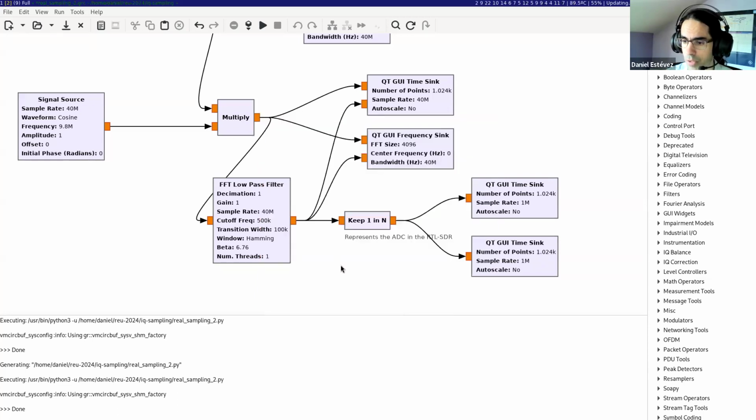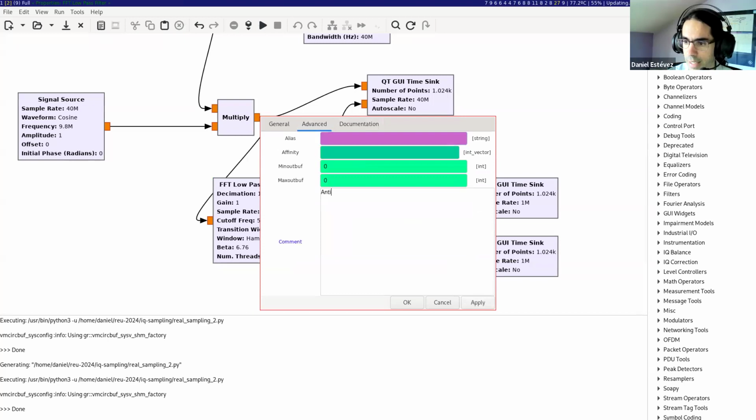if the filter doesn't remove it, it will appear here, but not as 600 kilohertz, because that's impossible. It will appear at 400 kilohertz. So whatever signal I had here at 400 kilohertz will become mixed with the 600 kilohertz signal that wasn't attenuated by the filter. When we use a filter for this purpose, which is to remove signals that would be aliased by the sampling, this filter is called an anti-alias filter.